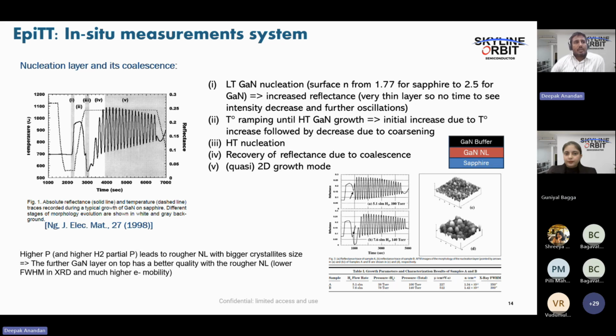Right now, if you ask me, silicon is being pushed a little bit away from the market, and gallium nitride is emerging. I would say most of the adapters and chargers have been replaced by gallium nitride HEMT structures. But as you mentioned, for mid and low power there will always be competition. Silicon carbide technology also wants to come into play, because it also gives better performance compared to silicon.